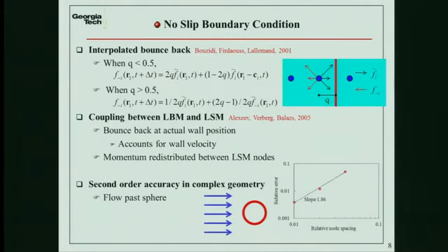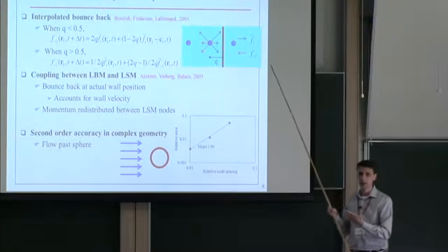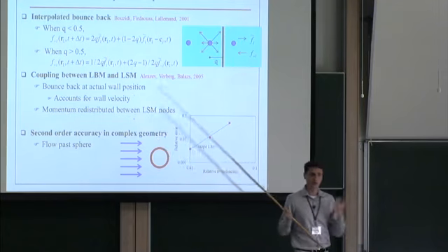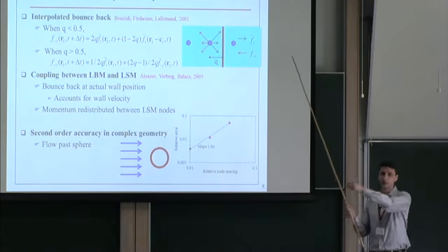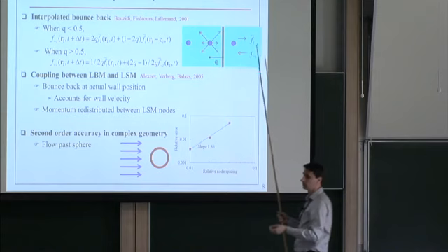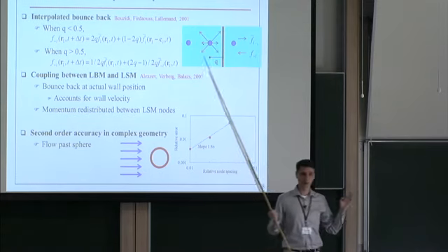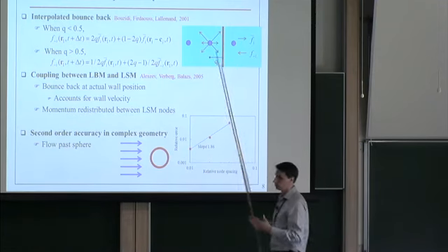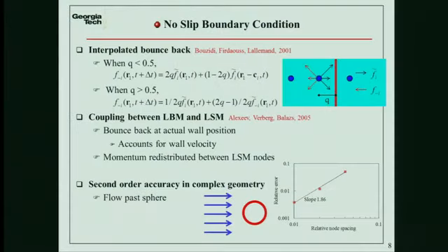Sorry. So the main reason we actually use lattice-Boltzmann for this fluid-structure interaction problem is that lattice-Boltzmann is very simple if we want to couple it with a solid. This is the boundary condition we use, essentially bounce back. If a fluid particle crosses the surface of my swimmer, we just bounce it back. That's it. That's the whole boundary condition, and it provides a no-slip boundary condition on the surface. We have a procedure to exchange momentum between fluid and solid, so we have a fully coupled system which conserves momentum.